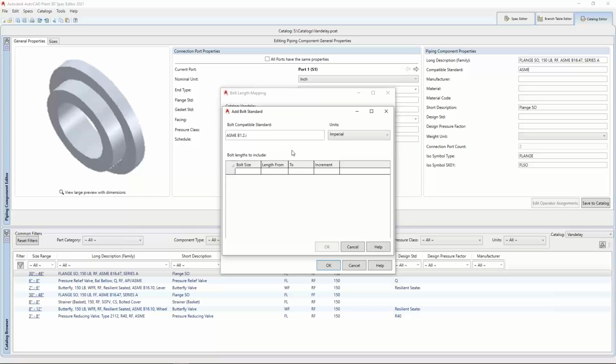You can use spaces, you can use punctuation and everything, but it's got to be matched word for word, letter for letter. And that also means it's case sensitive. So when I create the bolt, when I'm telling it what standard that bolt's using, it has to match this right here exactly. Upper, lowercase, everything. So that's why I like to do the copy and paste. I just put it in my notepad so I don't have any mistakes.